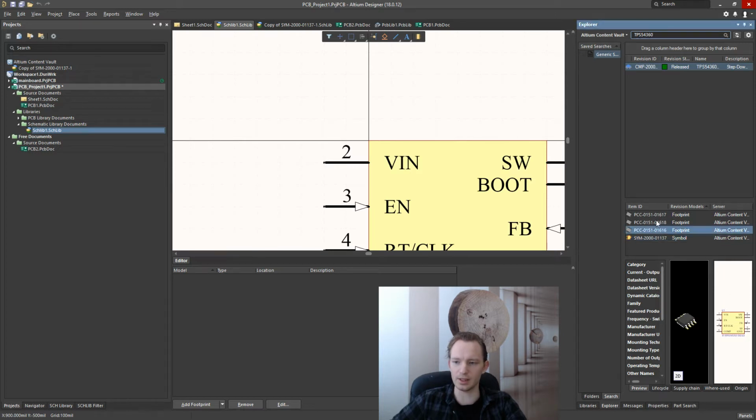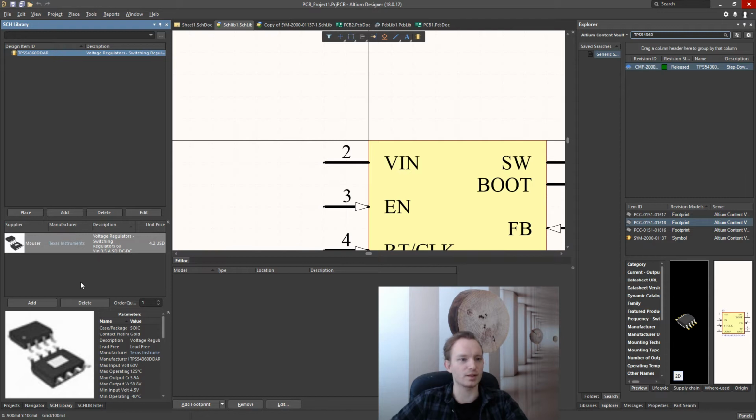Now, one thing that I really don't like about Altium Vault components is that the footprints are not named in any standard way. They're not IPC footprints. They're pretty much random. All of these components are created by people that don't really follow any standard; they follow their own standards. But I prefer to have the components and the footprints in a more standardized way. So the first time you do this takes a little bit of time, but luckily you don't have to do this every time you reuse the component later. So you only do it once for every component.